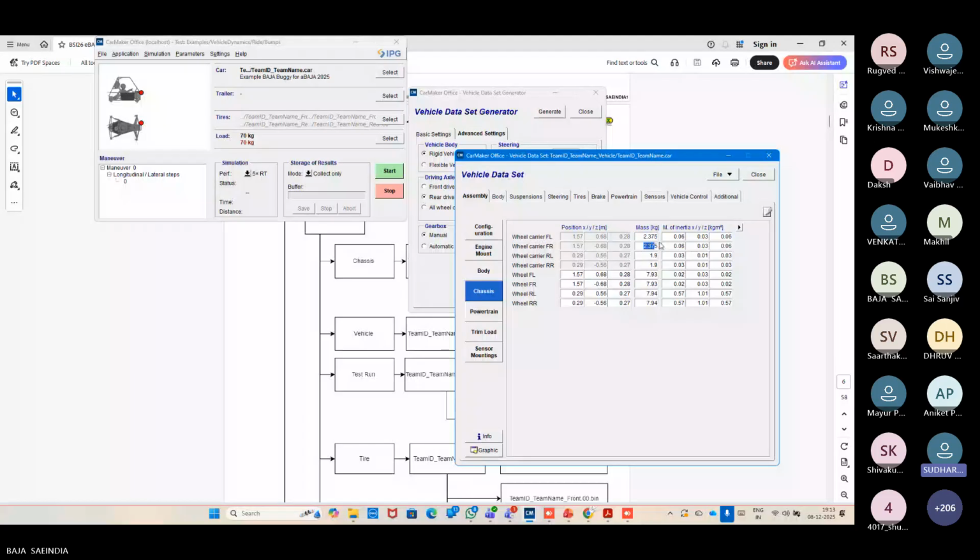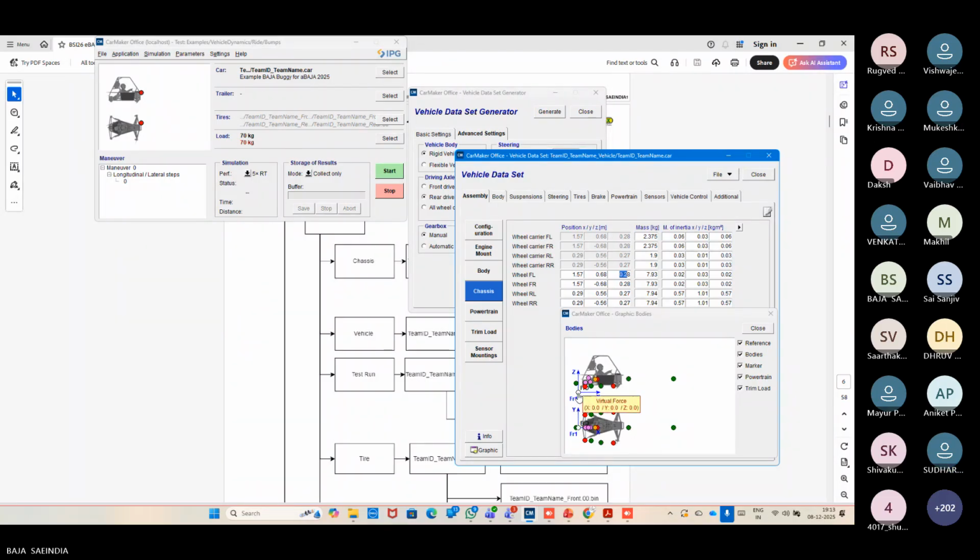And then for the position of the wheels you have mentioned in the design, you can measure it with the coordinate system. The FR1 coordinate system you should assign in your design. From that FR1 coordinate system, you should take a dimension for the XYZ components and you should enter it here.